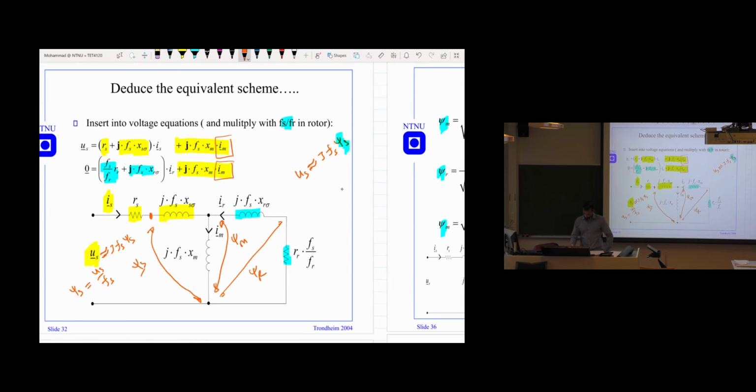In the first one, we keep CS constant, and you see that the other two fluxes, CR and CM, are reducing. That is one thing that we see from the circuit, because we are increasing the current but keeping the ratio the same, constant.